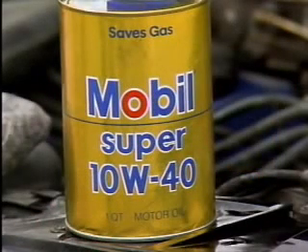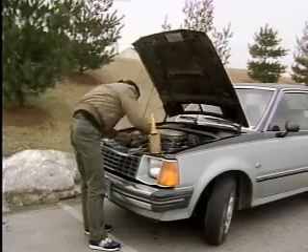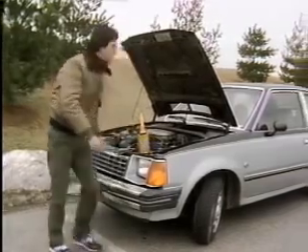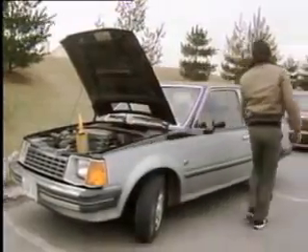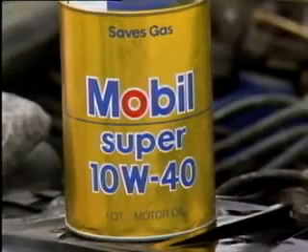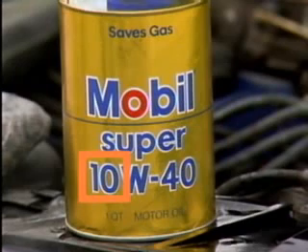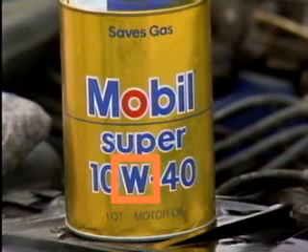Many oils, of course, have to be able to lubricate in both low and high temperatures. For that reason, many oils today are multi-weight. They combine the properties of a lower viscosity oil for low temperatures with those of a higher viscosity oil for high temperatures. A common example is 10W40 oil. At higher temperatures, it will have the properties of a 40-weight oil, and at lower temperatures, it will have the properties of a 10-weight oil. The letter W follows the weight that's associated with lower temperatures.